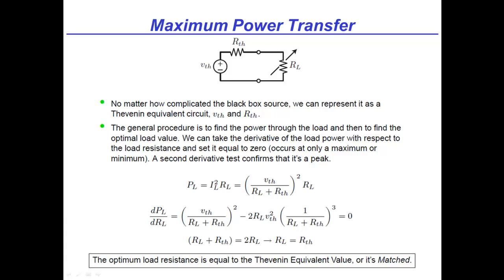Right. So another way to look at that is to do the second derivative test, which I sneakily avoided. You could take a second derivative and you'd find exactly what you suggested, that one of these is obviously the maximum, and then you get the minimum where you get 0 current because RL went to infinity. Good point. Got it. Yep. And so the optimum load resistance is sometimes said to be matched when this occurs.